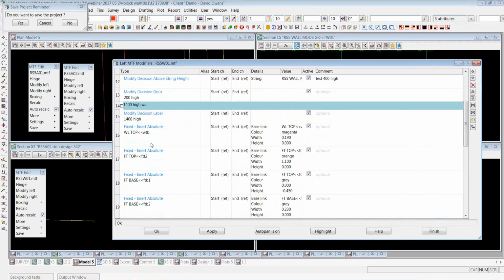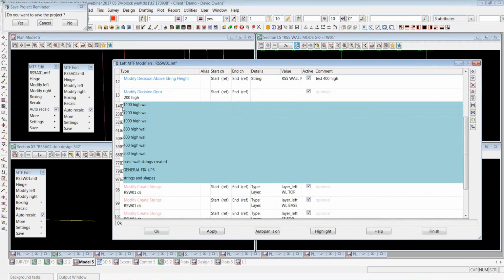So when I had a footing which was very, very small and didn't need that extra heel built into it, I still had to insert the same number of links, but effectively with zero height, zero width offsets, so that the actual physical shape I was left with was just a simple slab rather than a slab with that extra heel in it. So that was just one little quirk that I had to work around. It threw me for a while.